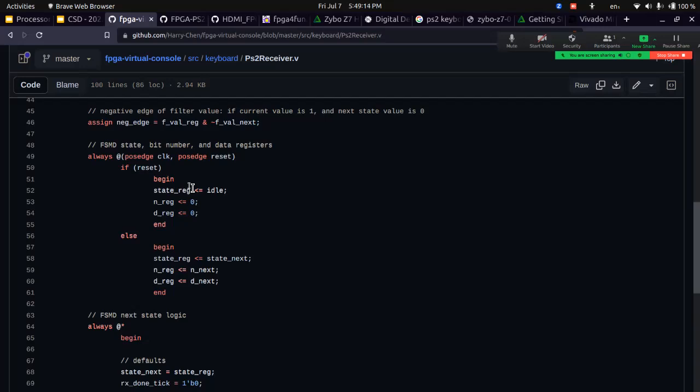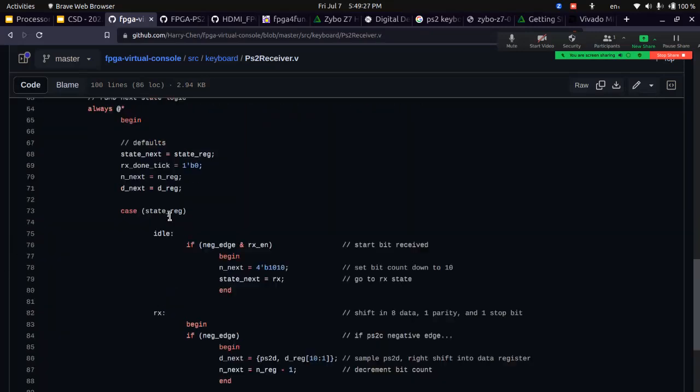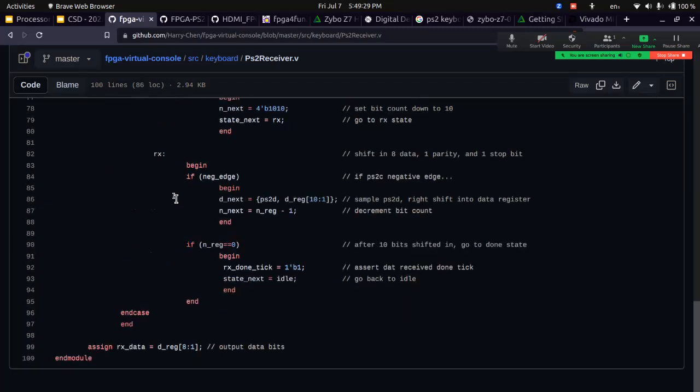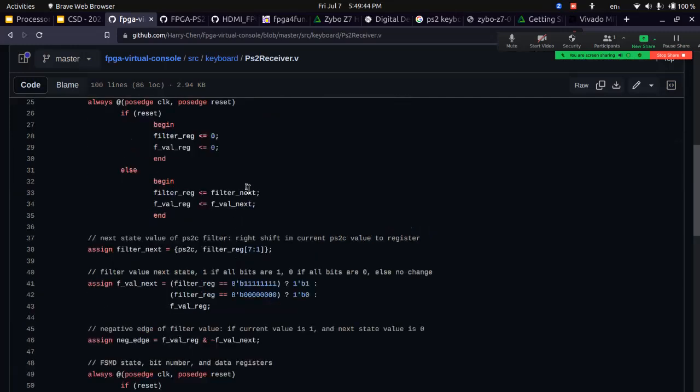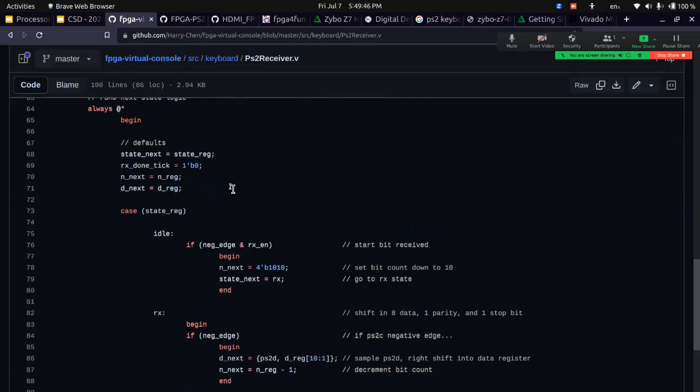You have to store the information that caps lock was pressed before, and until caps lock is pressed again, whatever you read, you should take as uppercase letters. Same way shift, and also num lock, everything. So that's a complex protocol, for caps lock, for shift, and also tab as special characters, but you can simply program for lowercase alphabets and numbers. That should be sufficient. No need to even do the arrows and other functional keys.